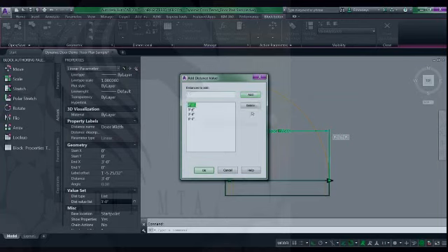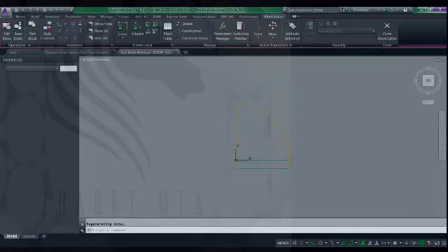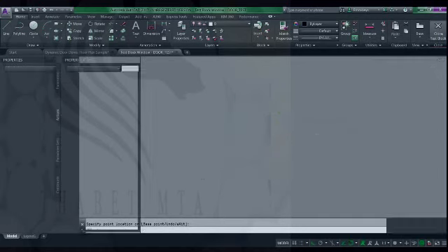And then if you think that you want to delete a couple later on, you can just come back in here and delete them however you want to add or delete. So I'm going to go ahead and say OK. And so you can see that that took effect by these light blue tick marks here. So those are preset dimensions that I have for my door width. So let's go ahead and test it to show you. Make sure that I applied it. Select my block. Then you can see it gives me my 38, 30, or 36. So far, so good. Let's close out of our test block.